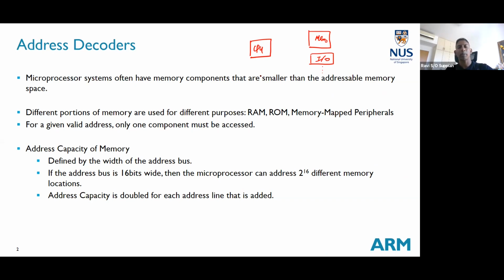When you write code and you want to update some data in the memory or read something from the memory, you need to communicate to the memory through three different sets of buses: the address bus, the data bus, and the control bus. The control bus is usually just a few lines, so we call it control lines, but you have the address and data bus. When I say I want to talk to the memory region, there must be some space that I have mapped it to.